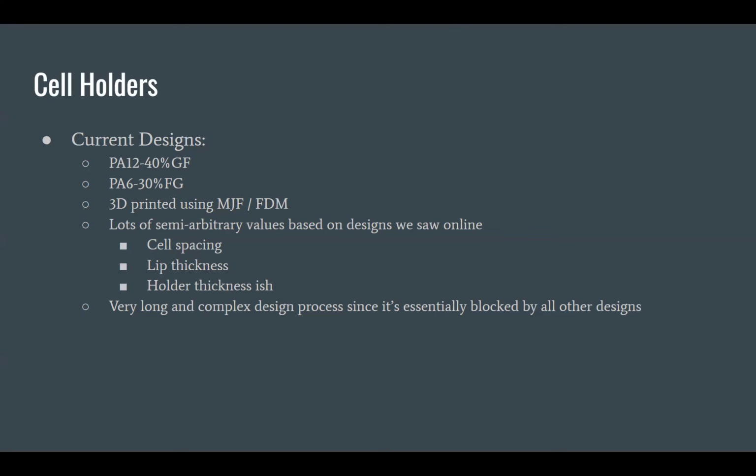Is there any regulations about how far apart they need to be? The cells? Yeah. So there are only regulations that say how far apart high voltage things have to be from low voltage things. From what I could find, I cannot find any rules that say what your spacing has to be between one high voltage thing and another high voltage thing.